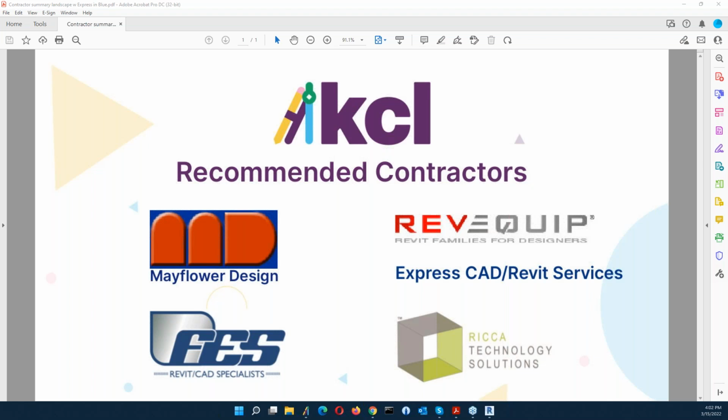We will look at some real basics. We will look at the file size. And honestly, if it's below 5 meg, we're not going to really jump on them. I know for some of you that might sound large, but most people have good Revit computers. It's not a killer if it's a few megabytes. We also look at the basic parameters. I cannot tell you how many times over the last decade we get a file from a manufacturer and there's no manufacturer or model number in that Revit family.